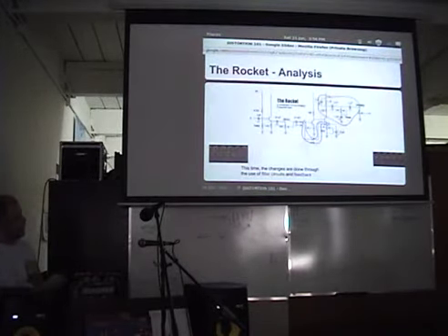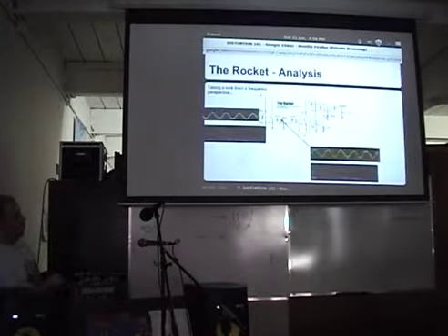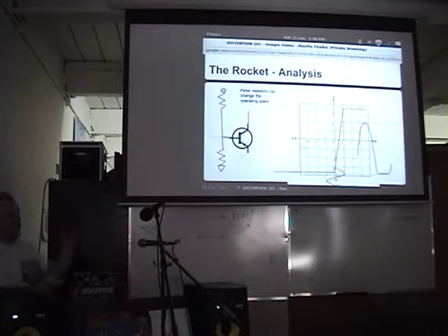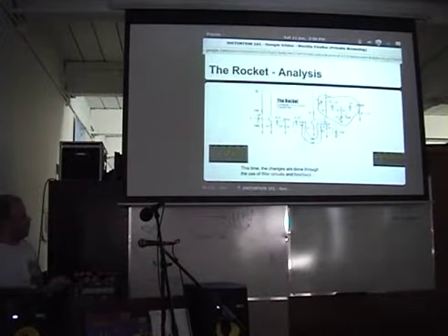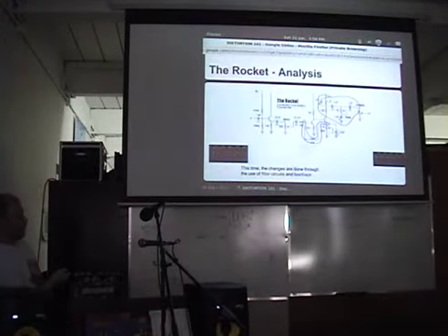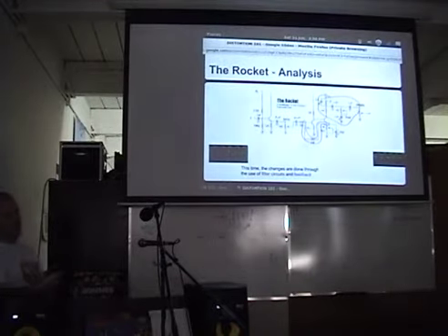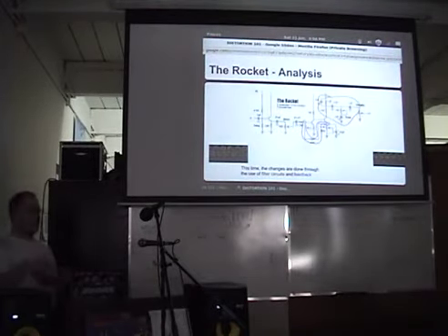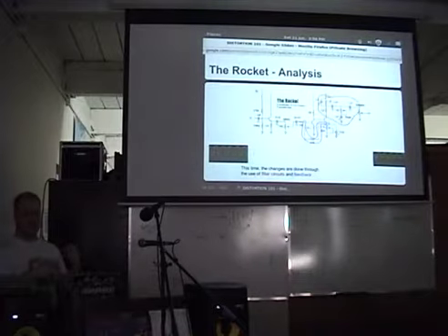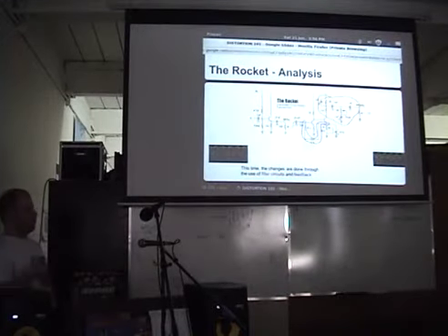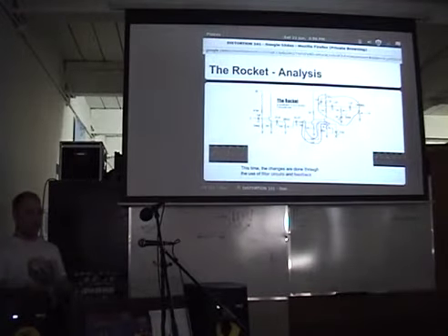So for instance, it's actually changing the operating point, if you recall, by increasing the bias voltage there. So when this signal gets louder here, it's shifting where this guy's transfer function is sitting. So that's where you can get interesting changes to the character of your distortion. And a lot of times, very similar circuits will have this stage done a little differently, and it can have really different sounding results.